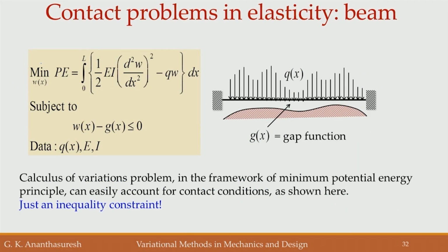Okay. And in mechanics, you can solve a number of problems. One of them is, let us say, a contact problem. Let us say I have a beam fixed on both sides, there is a loading, and below that there is a rigid structure of certain shape, a rigid surface, that is this boundary. Now, there is load applied, this beam will deform and might contact this surface at different points depending on how much load you are applying, and then deform like this.